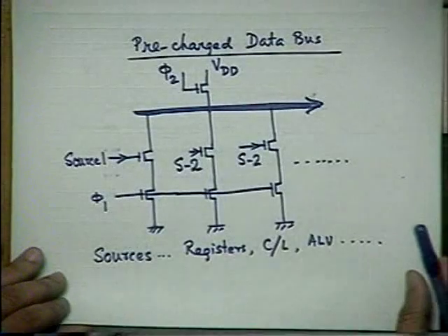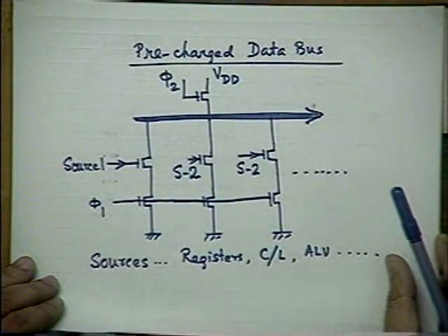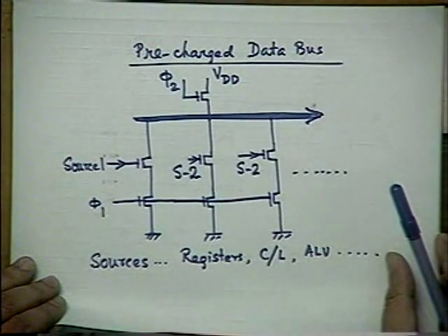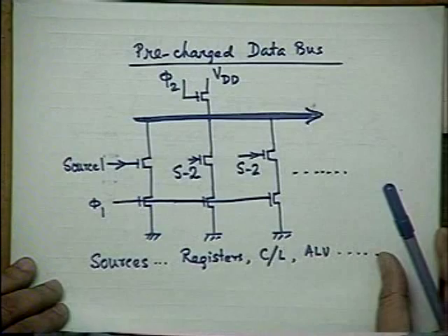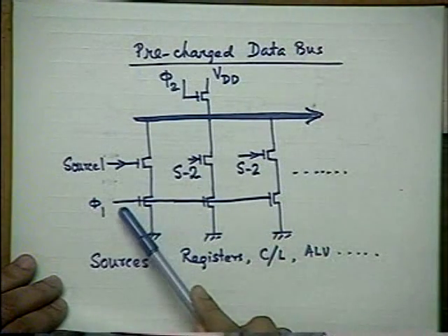One source will give the data, sir. In parallel, many sources of the same data, you have local shorting, because if one of the sources gives a 1 on the bus and the other source gives a 0, yes, you just have a local shorting. Yes. No, you know that.